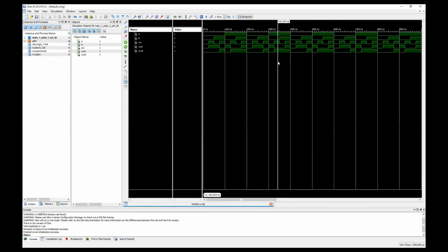Likewise, for another one, let's pick this one. If you see the A, B, and C input values, 1, 0, and 1, which means you're gonna have sum 0 and carry 1 again, right? So in here, this is the same. Let's pick another one in here. You can see the A, B, and C. A, B are both 0, but C in is 1. That's why I've got sum as 1 and carry as 0. So you can check it out to see if it's working.